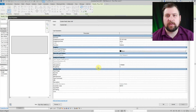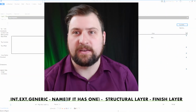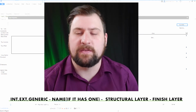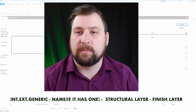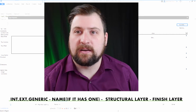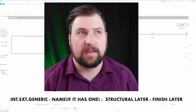So the best practice would be more along the lines of this format. It would be type, if it has one, so interior wall, exterior, foundation, some sort of descriptor of how that wall is used. The name, if it has one. The company I work for, a lot of times we call it like wall assembly 1 or wall assembly 2. And then the structural layer, so CMU, metal stud, wood stud, or anything else.